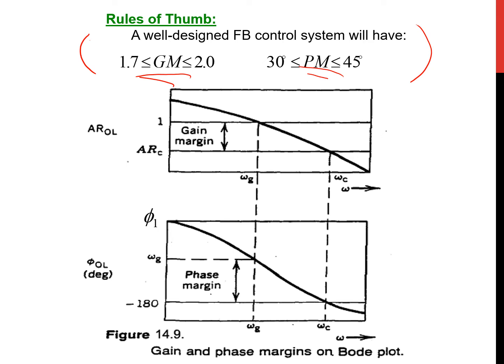Okay, let's take a look at the AR and the phase angle. Here, we start at negative 180 and draw the line until it reaches the phase angle line. This is WC. If we move the line up to the AR, it is still the same WC, because WC happens at negative 180.